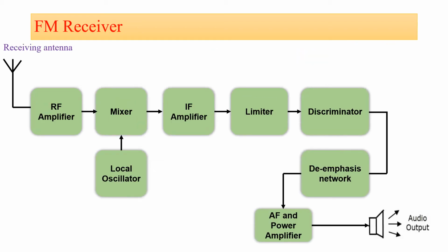This is all about the block diagram of the FM transmitter. Now let's see the block diagram of the frequency modulated receiver, or FM receiver. This block diagram is again similar to our AM receiver, that is the amplitude modulation receiver, and here two blocks, the amplitude limiter and de-emphasis network, are included before and after the FM demodulator, and the operation of the remaining blocks is the same as our AM receiver. We know that in FM the amplitude of the frequency modulated waveform remains constant.